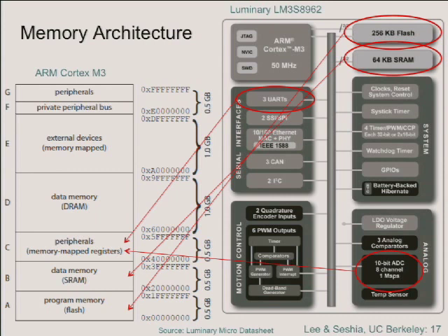UART's a very slow interface. As I said, it was designed in the 50s to talk to teletypes, so that's why it works. Yes, if these are UART connections, then by all means, multiplexing them in a multitasking context is very efficient. But if it's an Ethernet cable, it's a lot harder to do, because your context switches would have to be much faster. Or if it's USB, this USB is about 100 megabits per second. USB 3 is about a gigabit per second. So the speeds are really quite high on today's modern serial interfaces.